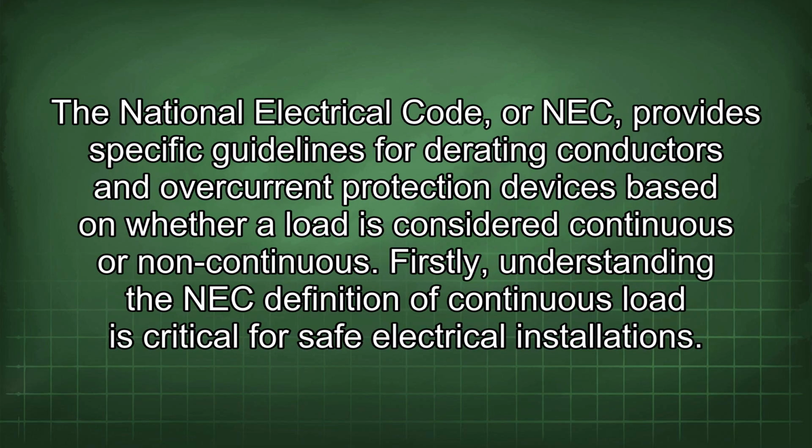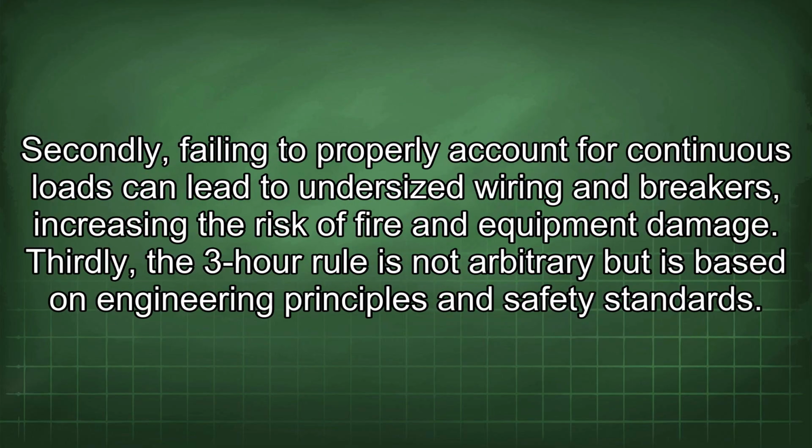The National Electrical Code, or NEC, provides specific guidelines for derating conductors and overcurrent protection devices based on whether a load is considered continuous or non-continuous. Firstly, understanding the NEC definition of continuous load is critical for safe electrical installations. Secondly, failing to properly account for continuous loads can lead to undersized wiring and breakers, increasing the risk of fire and equipment damage. Thirdly, the 3-hour rule is not arbitrary but is based on engineering principles and safety standards.